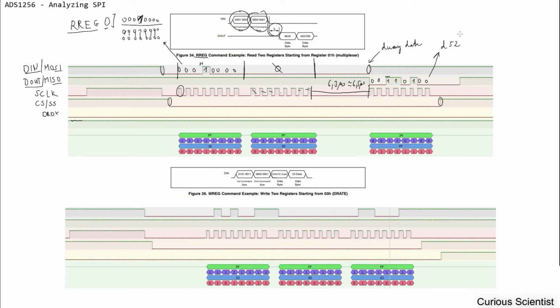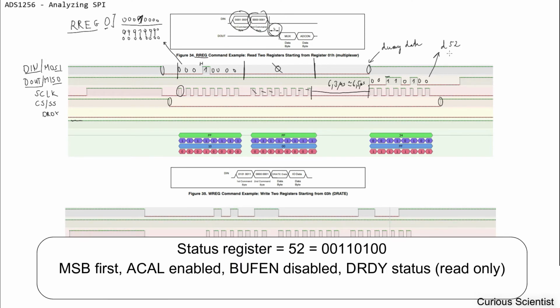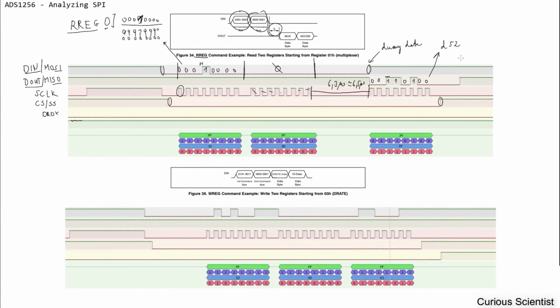And if you check the datasheet and compile the numbers for the status register, then you can see what my setting for this register is. And of course we can cheat, because here in this sequence we already have these data converted, but I wanted to show you that if you don't have this translation from your signal to the actual hexadecimal or binary numbers, then you can also just do it manually, because these are not too many signals.